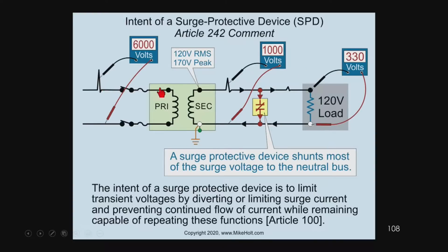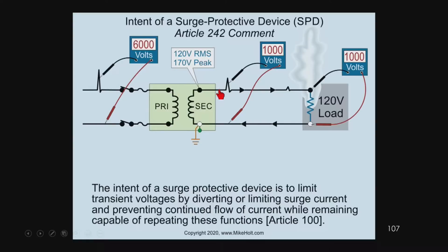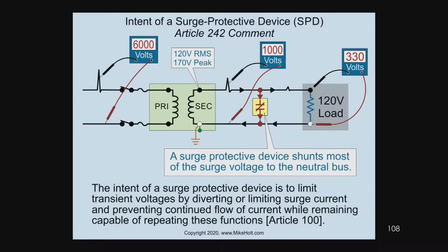You have this transient, and you have 1,000 volts coming in here, right? But there are rules on parallel circuits. Imagine that I put something here, and I put a resistor here with really, really low resistance, almost to the point that it's a short circuit. Now you say semiconductor, that could be off, it's an insulator, and then at a certain voltage, what is it, John, 330 volts? Well, yeah, there are different classes, but yeah, for example, 330 volts.